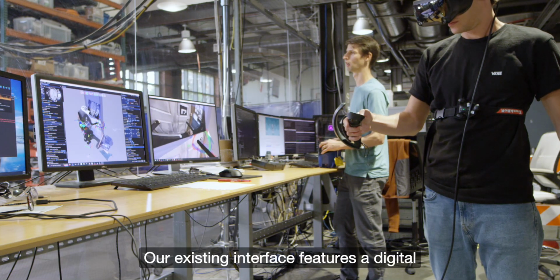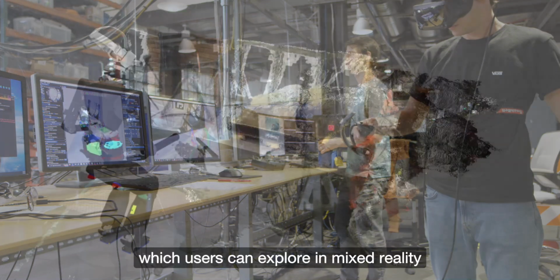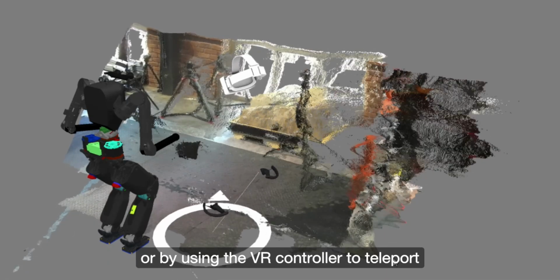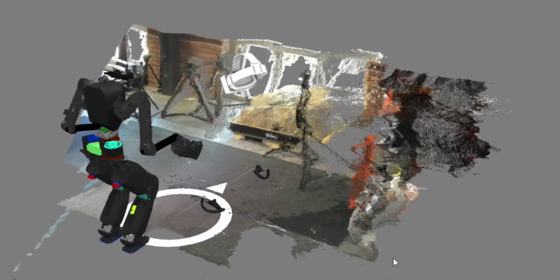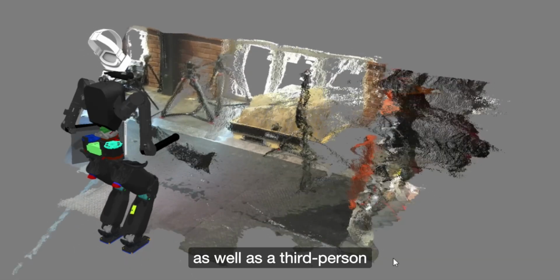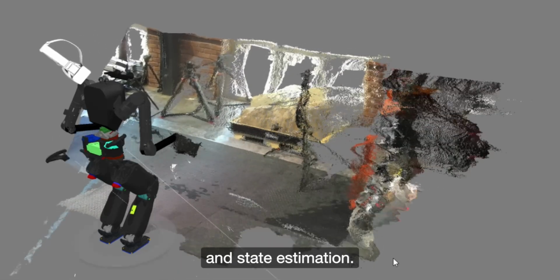Our existing interface features a digital twin representation of the world, which users can explore in mixed reality by physically moving or by using the VR controller to teleport to a desired location. This world view integrates all perception inputs from depth cameras as well as a third-person view of the robot generated from proprioception sensors and state estimation.